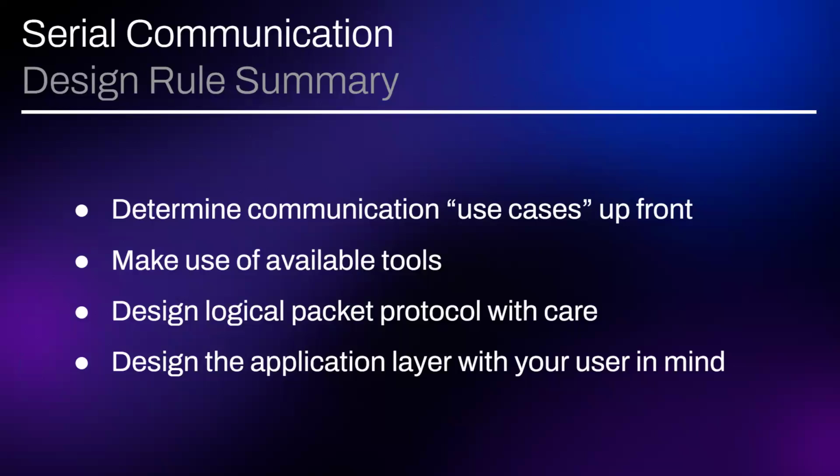One thing with serial links is you'll often have to configure both sides to be compatible. You'll say, here's your speed and here's your configuration, that 8N1. You have to tell both sides that. There are some that'll auto configure now. They'll see the data come in and go, it looks like it's this speed, and try to figure it out. But for the most part, you have to configure those. So there are pros and cons, but for the most part, serial wins, I think.